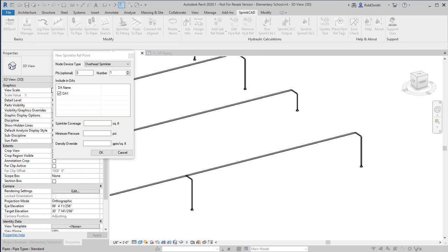And so this particular model of sprinkler head that is used is a sprinkler head that operates at 324 square feet based on 18 by 18 with a minimum GPM flow of 33. So I'm going to enter that 324 here as a coverage. You know that the density was set to 0.1, and density times coverage is going to establish the minimum flow rate for these sprinkler heads, so that would be 32.4 gallons.